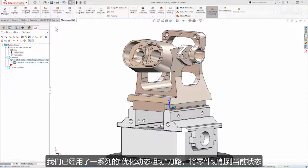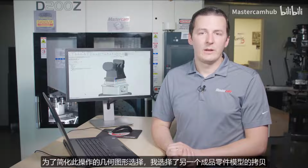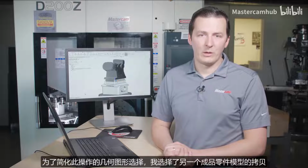A series of OptiRough toolpaths have been used to get the part to its current state, and we can see the remaining material in process by toggling the display of our stock model. To make geometry selection for this operation easier, I've altered a copy of the original finished part model.